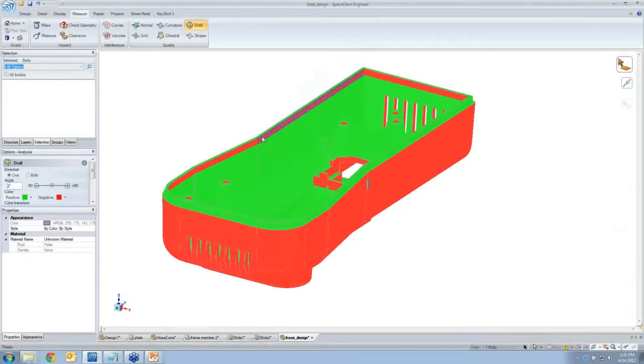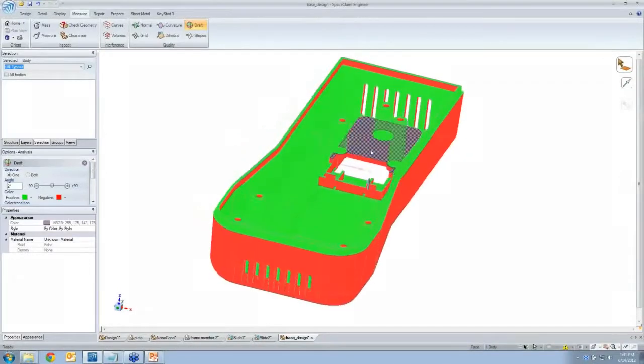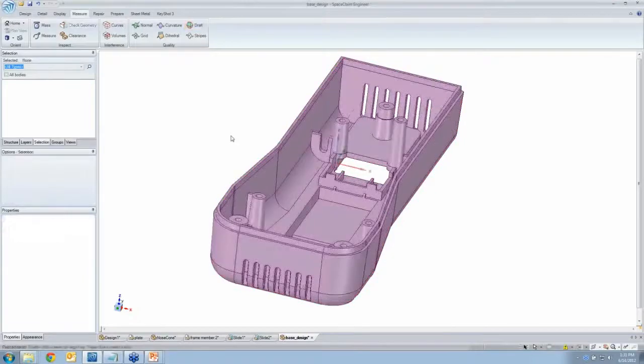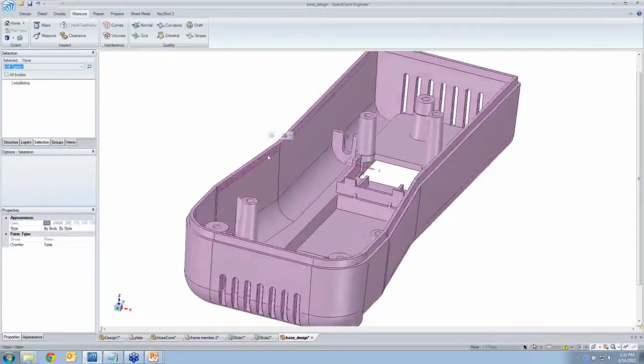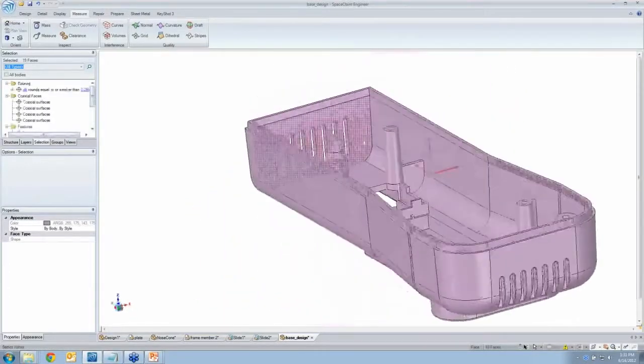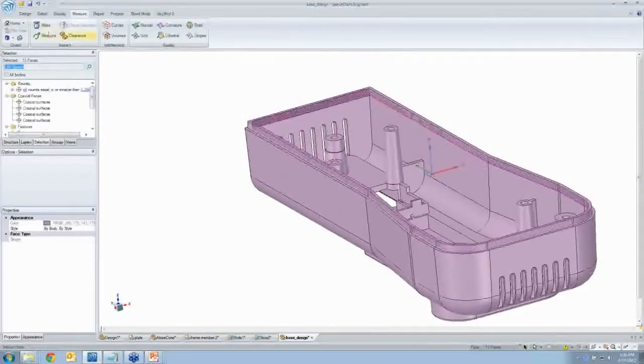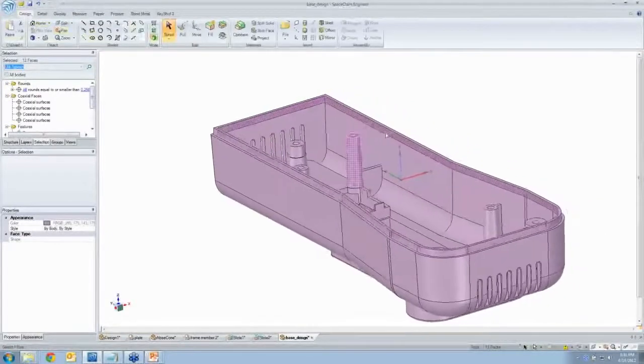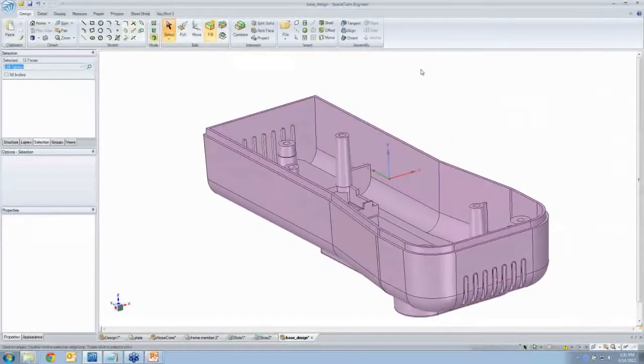You can see the perimeter, that ring around here that's red. So I need to take care of that, and then a bunch of things on the inside as well, towards the center. So let's just take care of both of those, and I think I'll wrap things up. All right, this perimeter, that ring doesn't have draft. There are a lot of ways to remedy that, but I think the easiest way would just be to get rid of those faces and let the vertical walls extend up. So I just fill in the faces. What's happened is that the vertical walls have just extended all the way up,